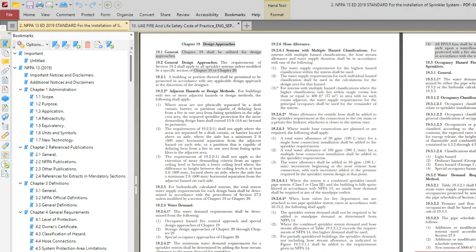Here the tank shall be sized to supply the equipment that they serve. Pump shall be utilized to supply the equipment that they serve. So this is just a general note. They are talking about hose, occupancy, hazard, residual pressure, everything. Residual pressure means the water pressure after the sprinkler discharge. For example, when the sprinkler breaks, the water should discharge at that pressure.